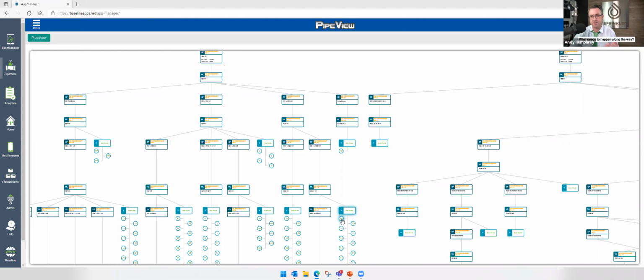Right. That was actually a fundamental code change, assigning the zone to a main line, not to a program. So you could have a program with 3 zones, and each of those zones could be on a different main line. Correct. Right. And so if we've got that scenario, what needs to happen along the way to make sure that any control points that may be in our hydraulic structure are in the right configuration to be able to deliver water to zones that may be on different main lines, right?